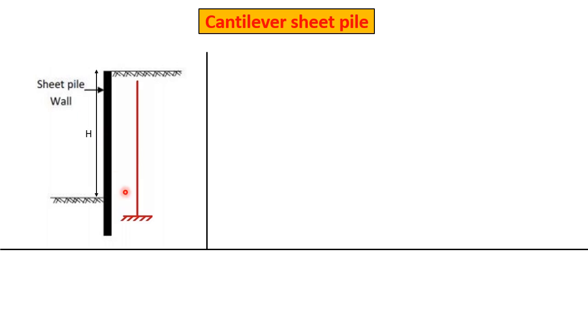And actually this flexible retaining wall acts as a best solution in weak soils, because if you have a very weak soil and you cannot satisfy the sliding, the overturning or the stresses criteria, you can use this type of retaining walls, which is called flexible retaining walls or sheet piles.